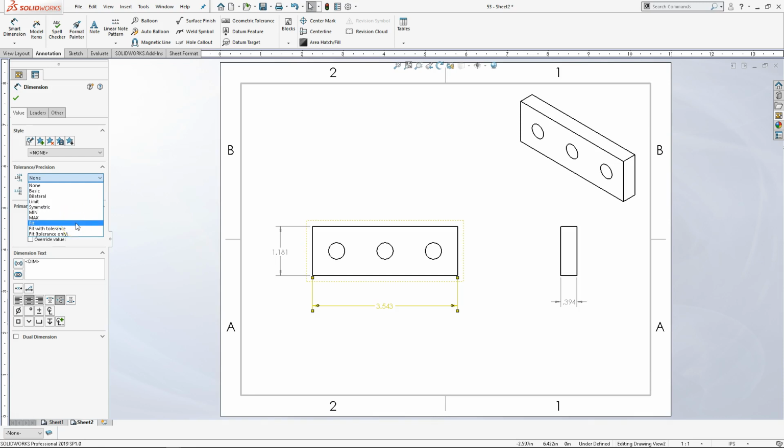Once you get over into the fits with tolerances, then we start looking at FN numbers or P numbers, and you go to the tables and you figure out, wow, does this need a hole that is 1,000th smaller, 2,000th smaller to fit the requirements of the fit? If it's a running fit, how much clearance does it need to have that running fit? All right, so once we picked,